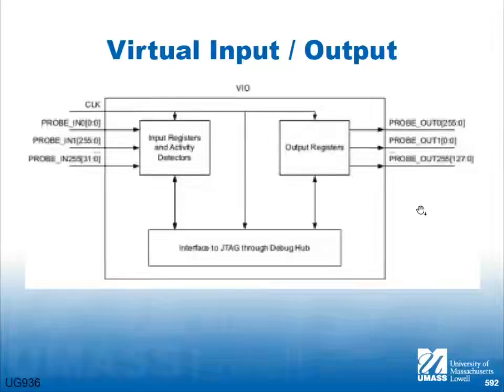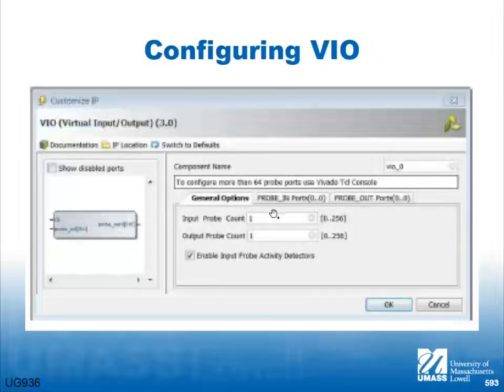But I've done exactly that. I've had like 8 profiles of signals that I wanted to put into the logic analyzer. I set them up separately, put it into an 8-to-1 multiplexer, and then took 3 pins out of the virtual output and connected it to that multiplexer, and then I could pick the profile. Again, worked really nicely. So you configure it similar to the way you configure the other one, how many probes and how many pins per probe and things like that. I've never done a significant number, like 3, 4, 5 kind of signals.